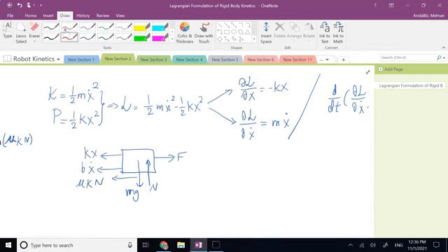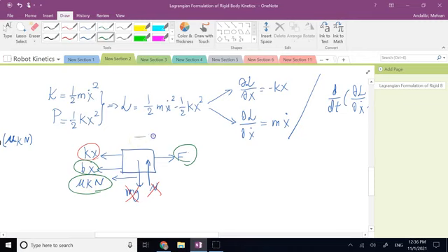And clearly here, as I said, this one is already taken care of. These two don't do anything. They are perpendicular to the direction of motion. The only forces that are non-conservative and you have not considered are these guys. And it's not really hard to show that. It is going to be, of course, F with plus sign, and then these two forces with negative sign, mu k N and B x dot, which are opposite to the direction of motion, right?